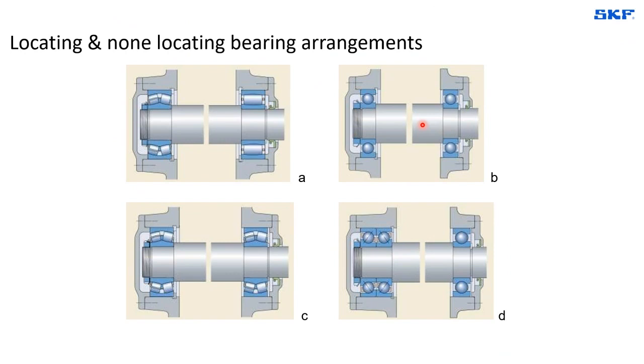Locating and non-locating bearing arrangements. This is again a quite basic concept of bearing applications. It's important to understand the bearing, like I said before, as part of a system. So in most bearing arrangements, maybe not in all of them, you will find this combination of locating, non-locating position.